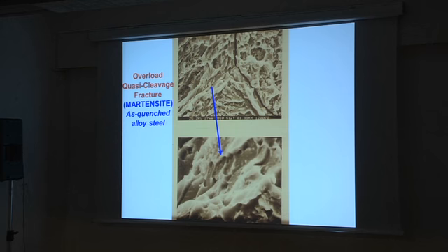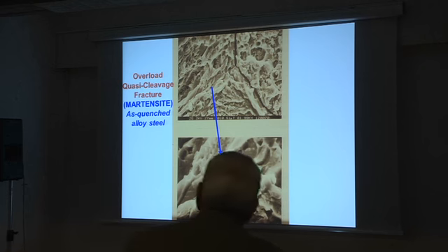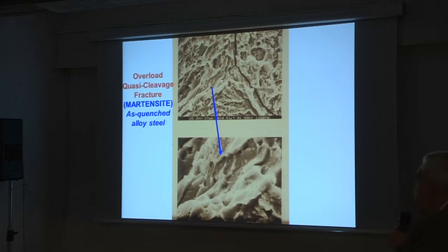assessing approximate fracture toughness from the surface that you see, and to have this you have to use the scanning electron microscope, SEM, because it has a depth of focus much higher than optical microscopes, then you can see the amount of absorbed energy that goes into the formation of these little holes.